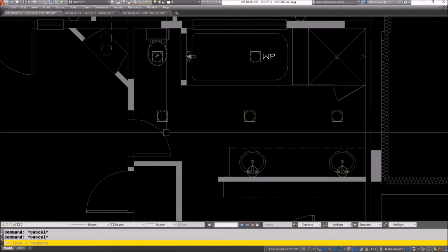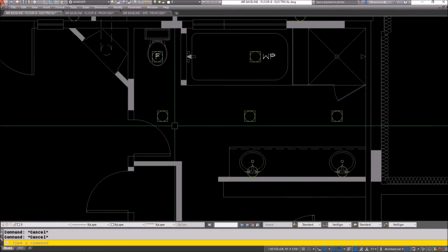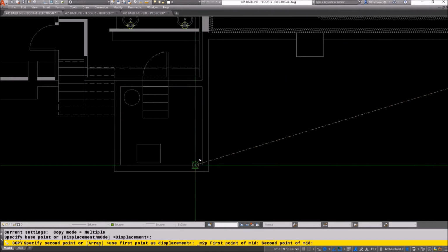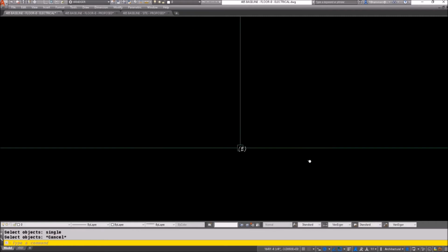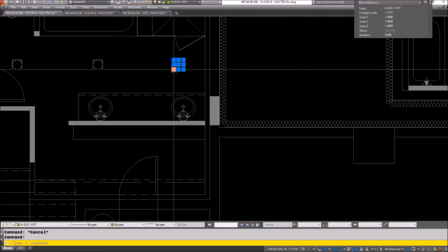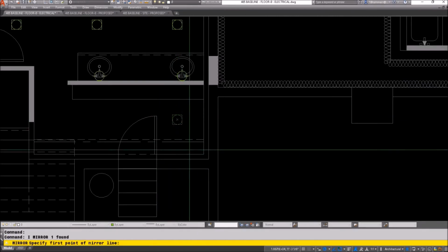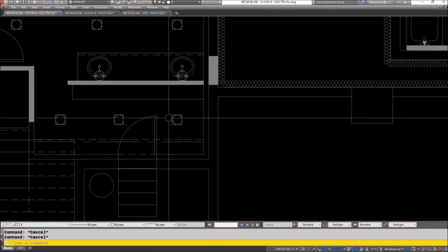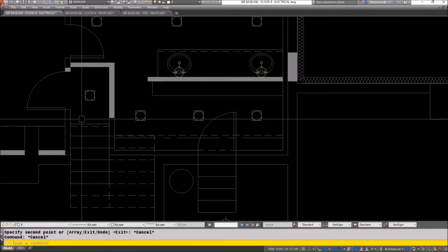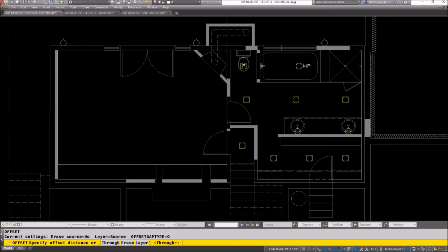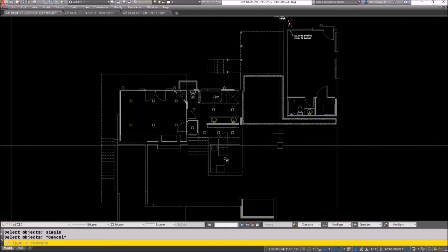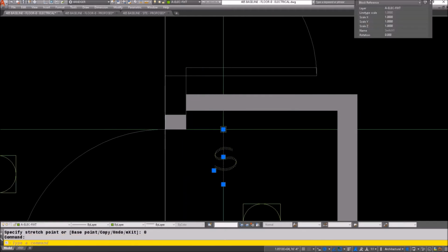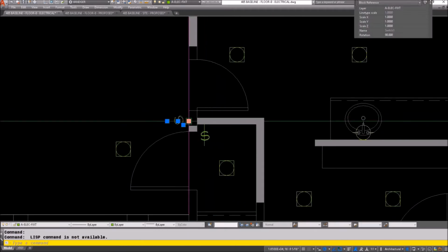Here's how I lay out the geometry for this. I'm going to probably line this up with the center. Usually when you're doing lighting, you want to lay it out to some kind of grid, so I just matched that to the room. Here's what I'm talking about. See how I laid that out? Just offset it 36 inches from the perimeter, and then put the cans in on the points.